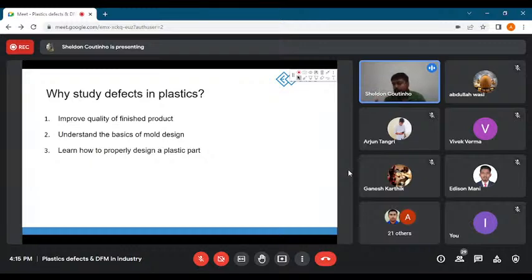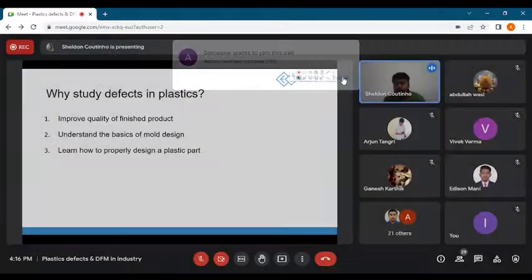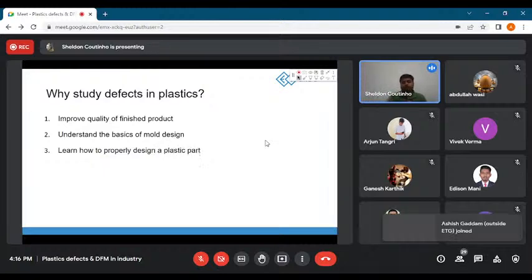Because after you have designed it and it went through manufacturing, perfect, you designed it for manufacturing. But when it goes to assembly, if there are 10 parts that are identical, but they need to go in specific places, the workers on the assembly line wouldn't be able to do it because they are not the ones who have designed it. You as a designer, if they give you the product and say, place these parts where they're supposed to go, you will do it quickly because you designed it, but they have not designed it. So that's where design for assembly also comes into place.